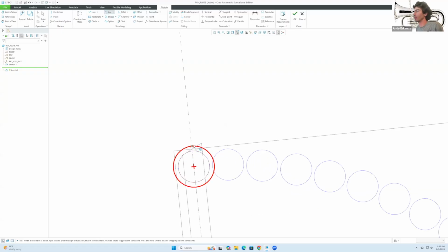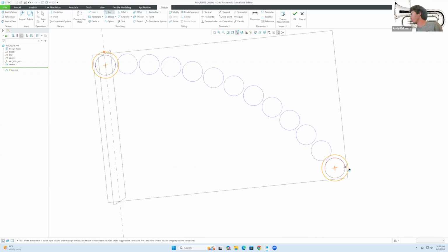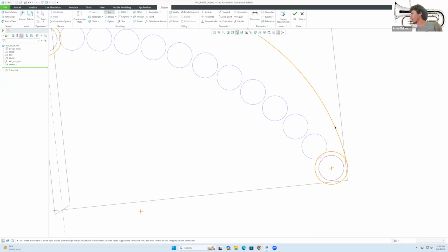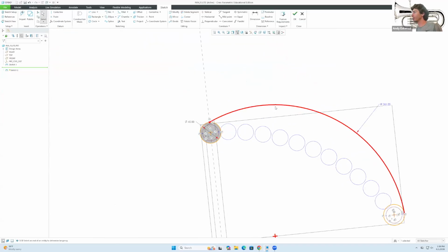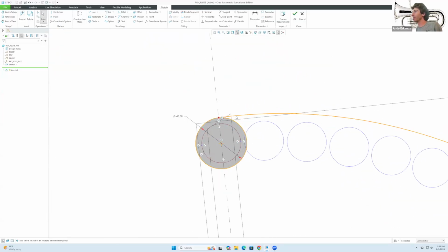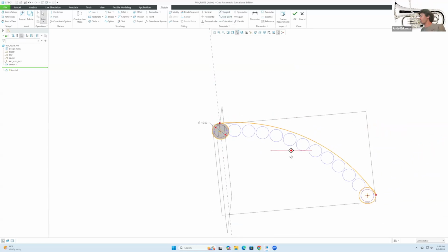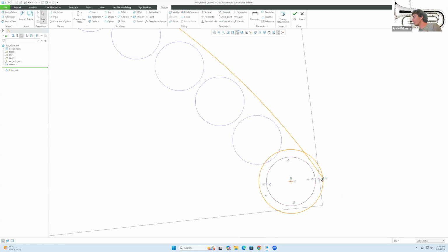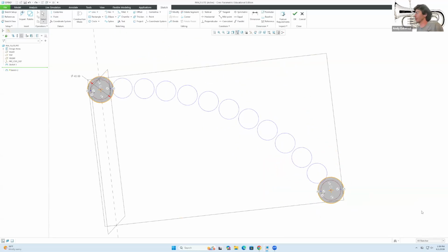One that will go from that point all the way to that point. It's gonna be like that, but I'm wondering if I can click on this line, I can click on that line and make those two tangent. Or actually, maybe the order is tangent, then 1 and 2. There we go. So now we have like 2 lines that are there. The only problem is that I believe I should have chosen a different point on that end there. So let me go ahead and do that one more time.